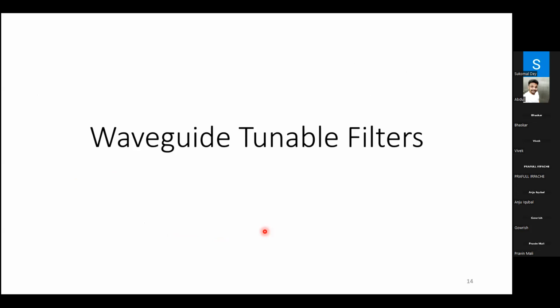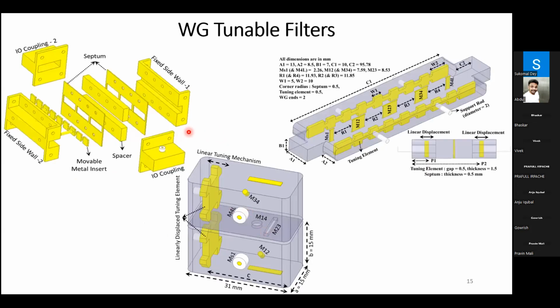In waveguide technology, I will be presenting 3 tunable filters we have developed: one using a single tuning element, an all-pole filter; a single tuning element filter with transmission zeros; and a bandwidth reconfigurable filter.